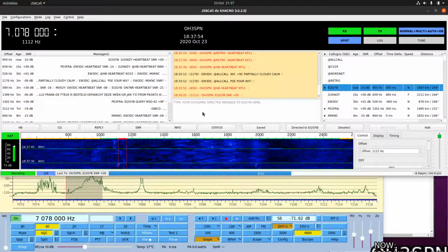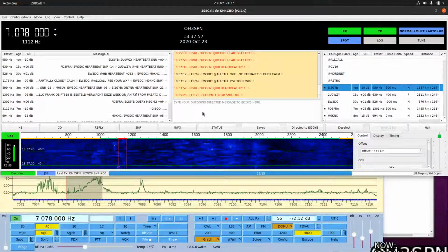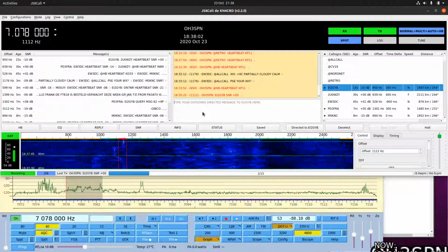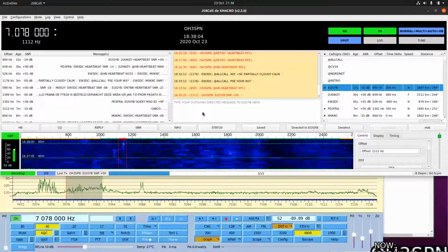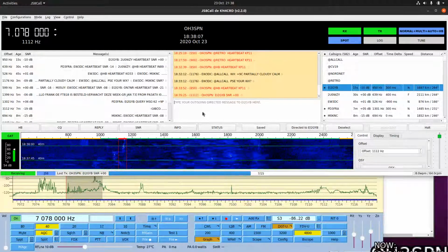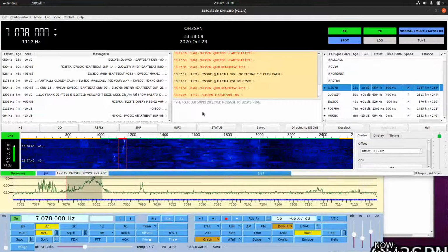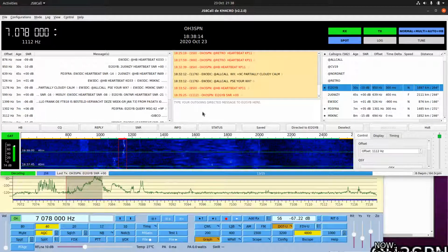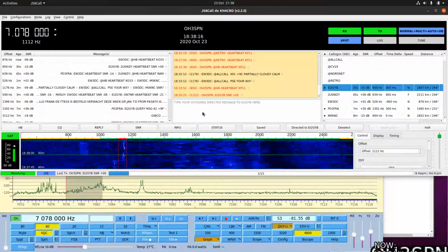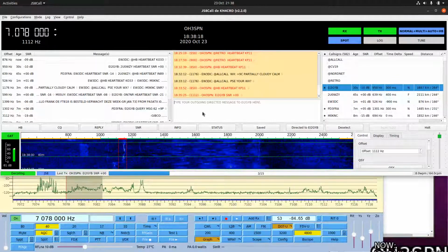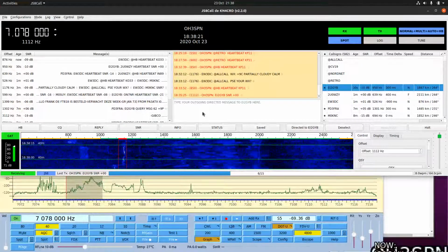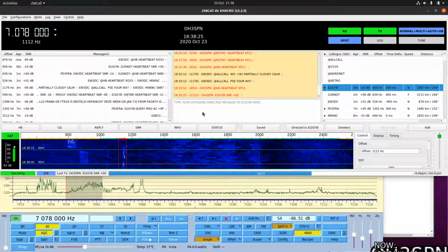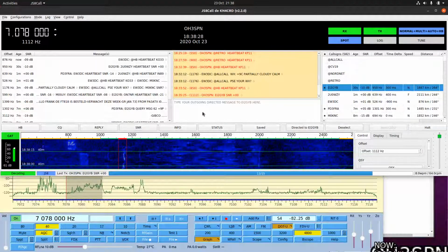So you've got to keep in mind, SNR, the signal to noise ratio, is a better comparison, but it's still in relation to something. It's still in relation to their noise floor. And it's one of the things that bugs me on SSB: you'll speak to someone and they'll say, oh, you're S something, but I have S9 noise. It's like, well, that's meaningless. If you have S9 noise, at least on SSB, you can't meaningfully hear anything below that.